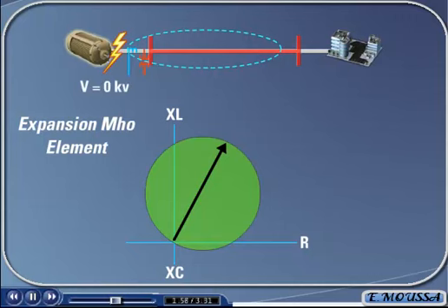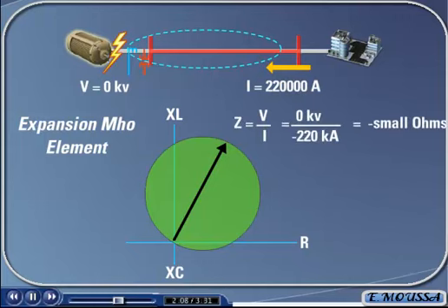If a fault occurs just before the beginning of the transmission line, and the transmission line is double-ended or multi-ended, current will flow into the CT from the opposite direction. If the relay now calculates the impedance of the line, the value will be negative, and plotting that impedance point will put it very near the origin, but in the reverse direction to the transmission line.